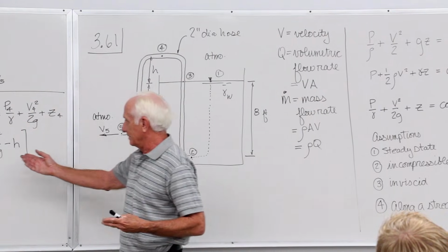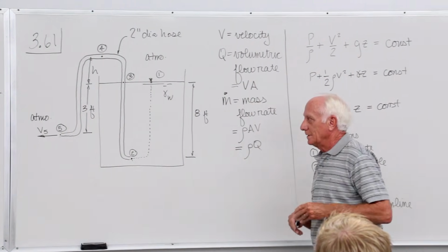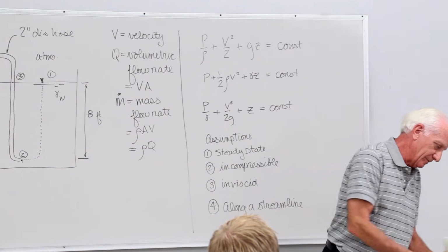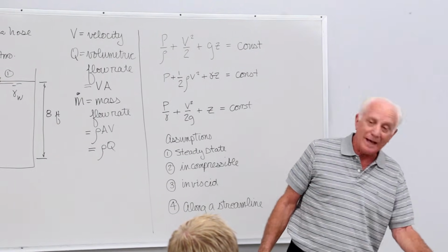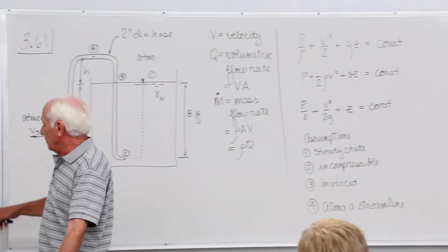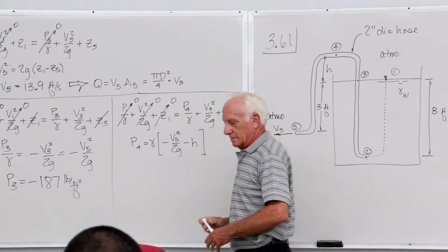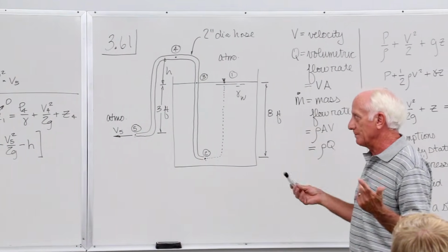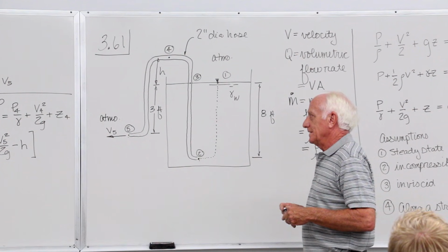Well, you know, this gauge pressure plus 14.7. The vapor pressures in here, it says right there in the column, are absolute pressures. So watch out. That's gauge, okay? You have to watch your units, absolute or gauge.